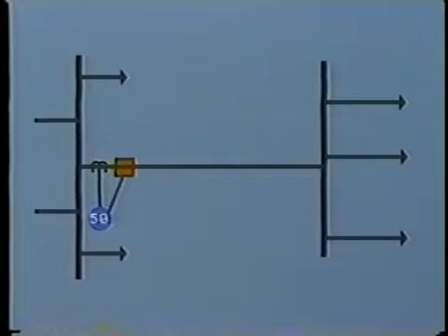This instantaneous action can prove to be a problem at times. For example, if a large consumer load is started, say a large motor, it will pull a considerable surge of current for a few seconds. This may well be high enough to trip the instantaneous overcurrent relay, and so isolate the whole feeder, including all other customers. To avoid this, the operating pickup must be set to a very high level. And certainly this would be adequate for protection.